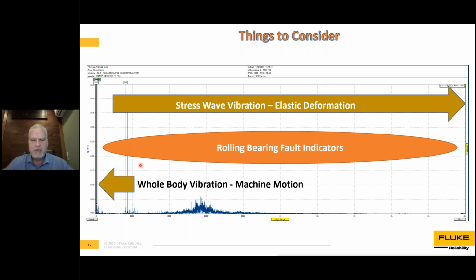This is oftentimes why we refer to low resolution wireless sensors as hand raisers, because they won't catch any of this early detection. They'll only catch it just before it fails, which is when we start seeing those kinds of failures in the low frequency ranges.